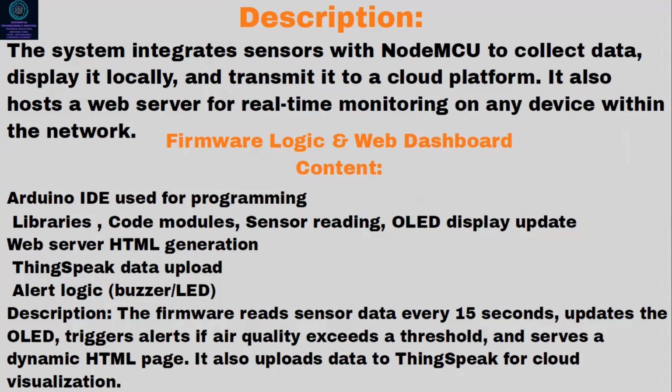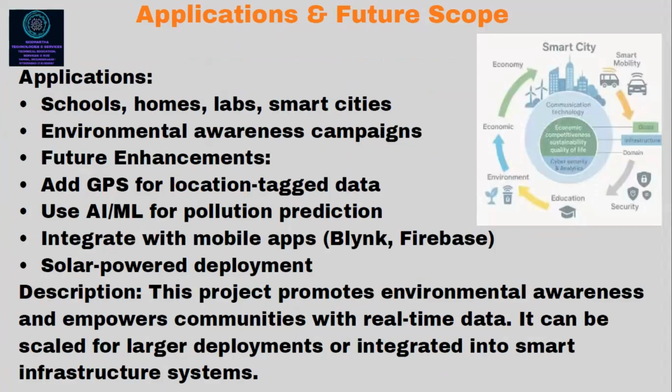The description: the firmware reads sensor data every 15 seconds, updates the OLED, triggers an alert if air quality exceeds a threshold, and serves dynamic HTML pages. It also uploads data to ThingSpeak for cloud visualization. Okay, so this is our project.